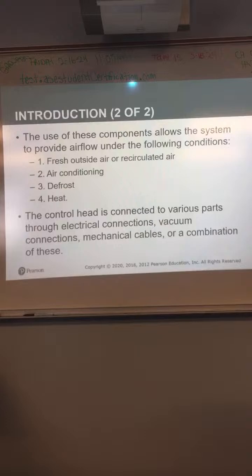So what causes windows to fog up? Depends. You mean after you turn it on? Yeah, so like say you have it on and you have the heat or recirculation. Okay. Here's the deal. Normally, if you have your heater on and you're trying to defrost a windshield or something like that, the AC compressor will come on. And what it does is it takes the moisture out of the air so it doesn't fog the windshield up, and it will clear it instead of making it worse. So normally that's what's going to happen.